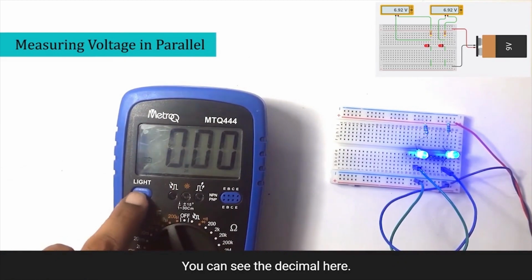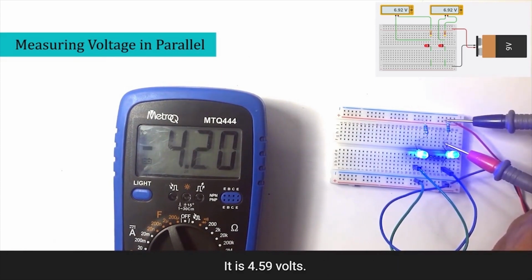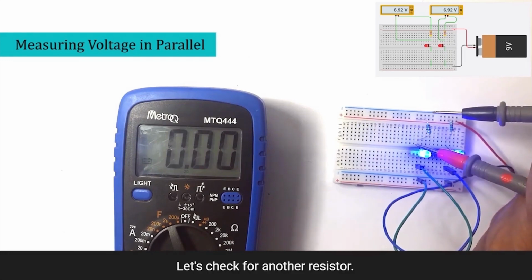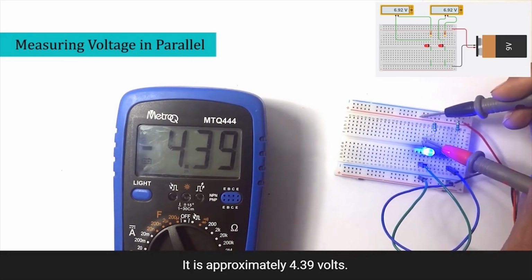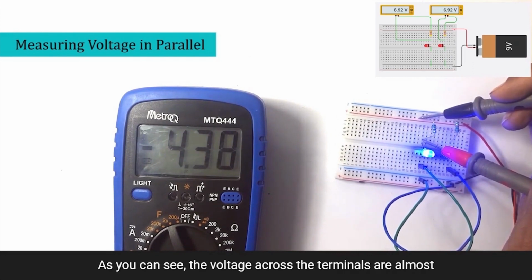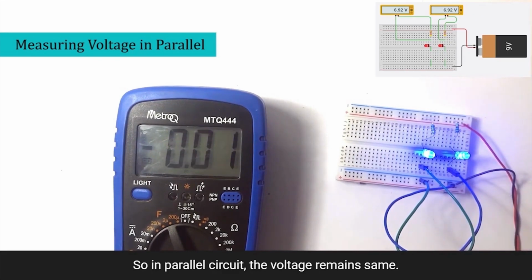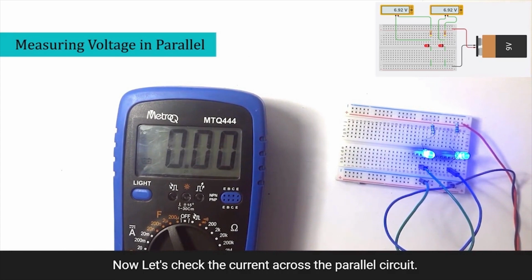You can see the decimal here. Now let's check the voltage across the first circuit, that is the first LED. It is 4.59 volts. Let's check the other resistor. It is approximately 4.39 volts. As you can see, the voltage across the terminals is almost the same. So in a parallel circuit, the voltage remains the same. Now let's check the current across the parallel circuit.